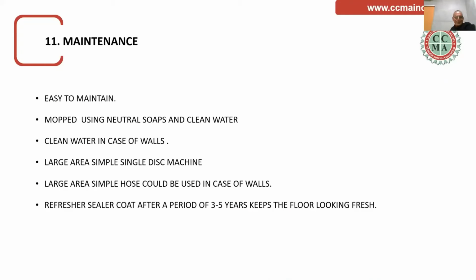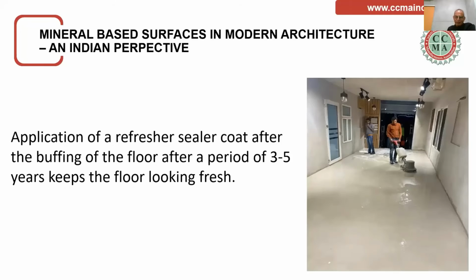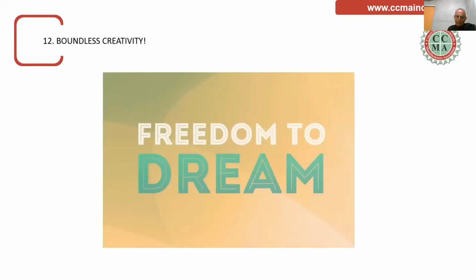And finally, the maintainability. All these floors and wall finishes are easy to maintain. Normal mopping with clean water and neutral soaps is enough. In case of large areas, the use of a single disc machine with a white pad is recommended. These are the same machines we normally see in hotel lobbies while the maintenance is on. A refresher coat of sealer is recommended for heavy traffic areas after 3 to 5 years. In summation, mineral-based surfaces allow for complete freedom to dream.